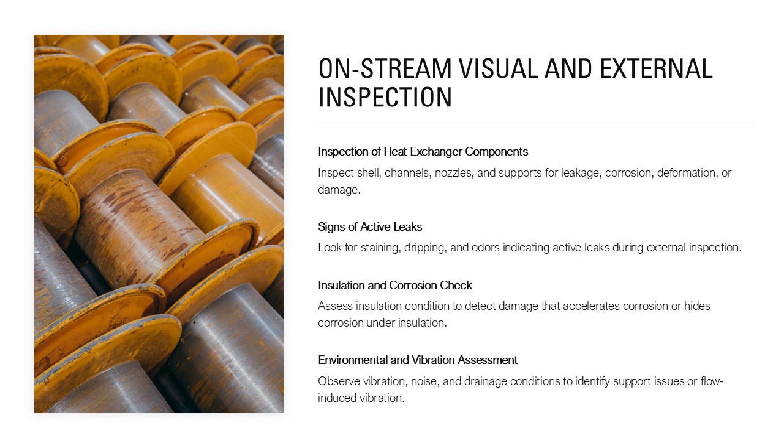Inspectors should examine the shell, channels, nozzles, and supports for signs of leakage, corrosion, deformation, or mechanical damage. Evidence of staining, dripping, or product odors may indicate active leaks. Insulation condition should be assessed, as damaged or missing insulation can accelerate external corrosion and may hide corrosion under insulation.